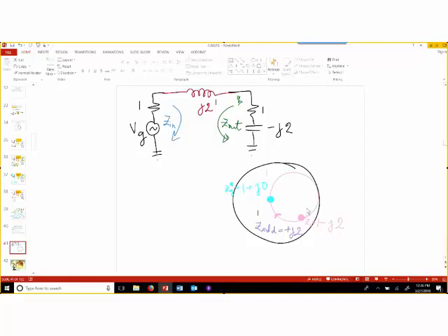When you add two impedances, the elements are in series. So if you look from this direction, you see that the input impedance is 1 plus and minus j2 cancel, so it's just 1. If you look from the output, from the load side, you see that the impedance is 1 plus j2, which is the complex conjugate of the load, right?